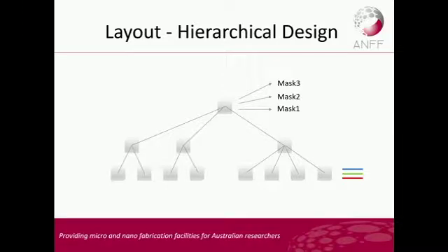So for L-Edit, we can do a sort of hierarchical design. If you spend a bit of time up front figuring out what you want to do with your design and how you're going to lay it out, then you can make a design that's easy to just print your masks off from at the end. It also means any future updates are very easy. If you need to go back and make a change to your design, if you use this sort of format, it makes it a lot simpler to change later on.